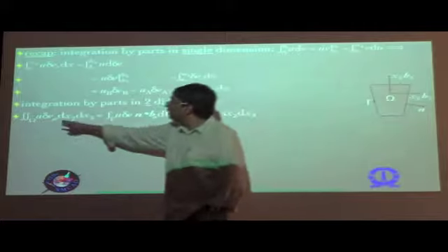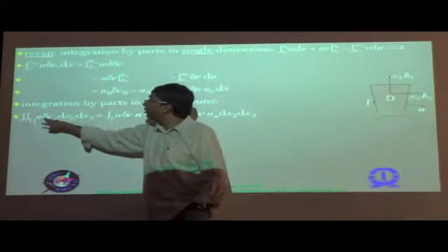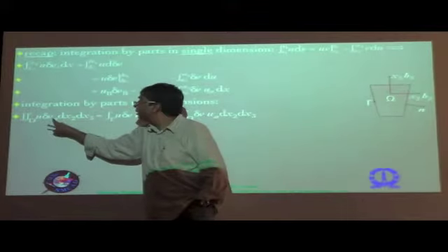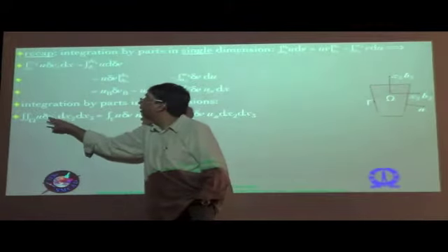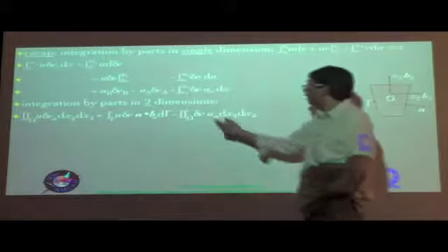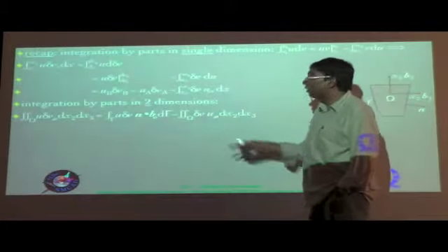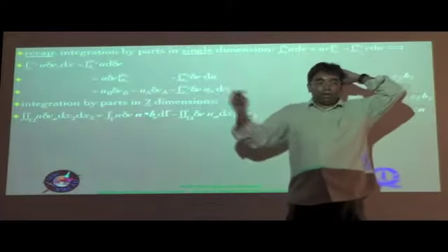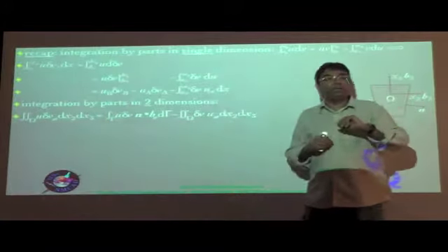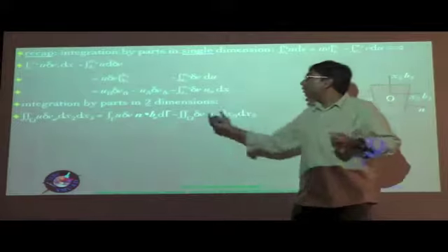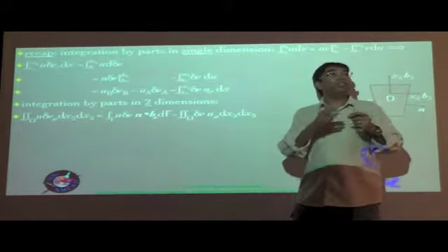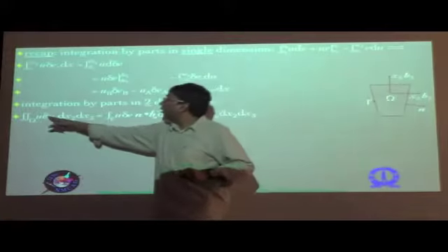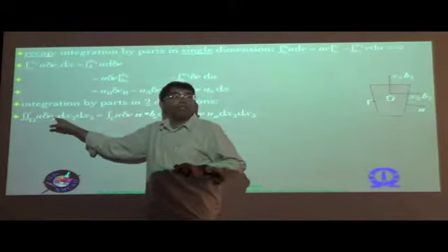And now you see that this derivative has been shifted from the variation term to the function term. In other words, you have a u comma alpha instead of a delta v comma alpha. Because eventually, to get the so-called Euler-Lagrange equations, or the governing differential equations for the system, we have to collect the coefficients of the variation of each of these variables, and so we cannot have the derivative of variation over here.